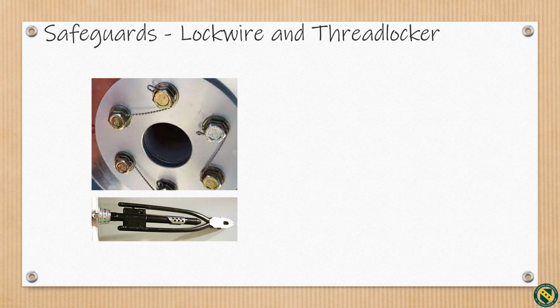Safety wire, or lock wire, is a type of positive locking technique that prevents fasteners from falling out due to vibration or other dynamic forces. A fastener typically has a drilled through hole that the wire is passed through, twisted, and anchored to a secondary fastener or part. Bolt heads in the rotating shaft flange pictured are lock wired in pairs. The presence of safety wiring may also indicate that the fasteners have been properly torqued, a witness wire.